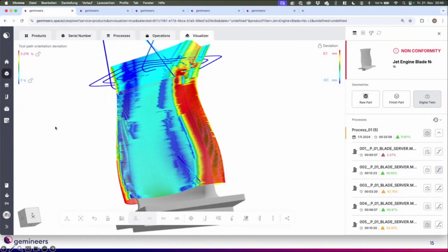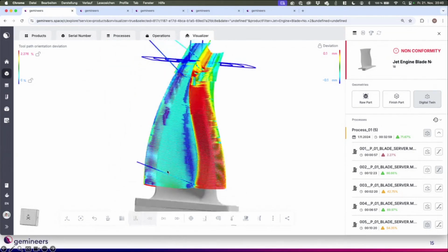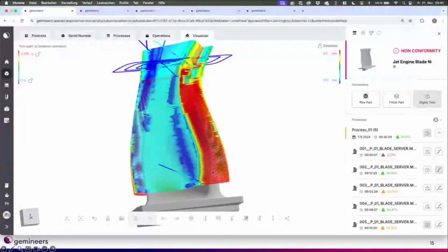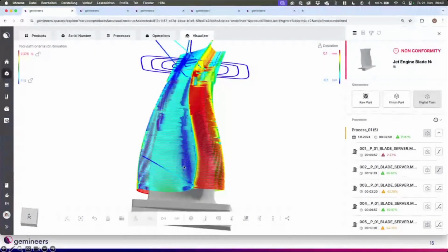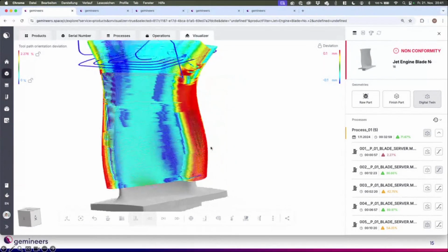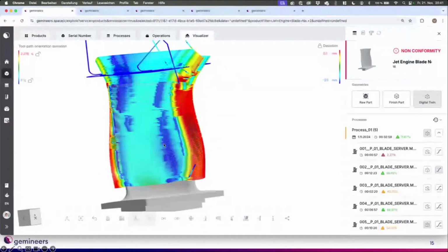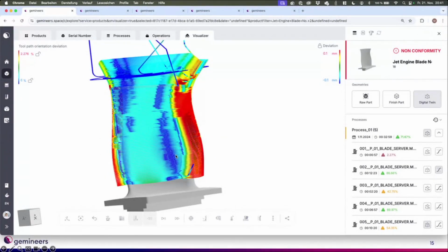So to get the rabbit out of the box, I don't know if it's also something you say in the US, to unveil the magic, is what we did here, because we wanted to create this deviation. We played around with the cycle H32 and made the toolpath tolerance a lot bigger. So the machine moved a lot faster over the corner, causing and tolerating this toolpath orientation deviation, which it normally wouldn't do. And here we have the data.